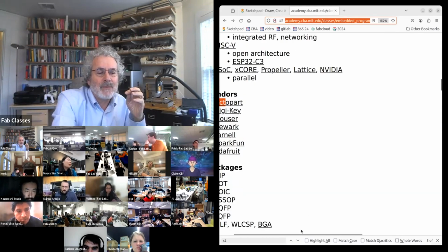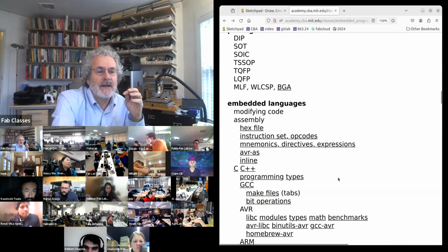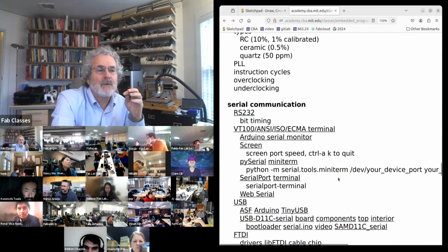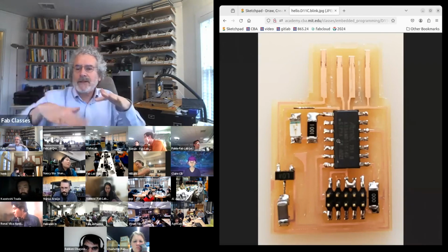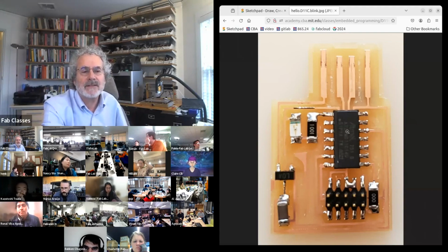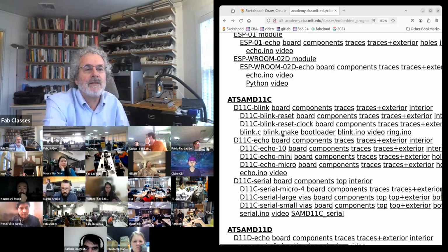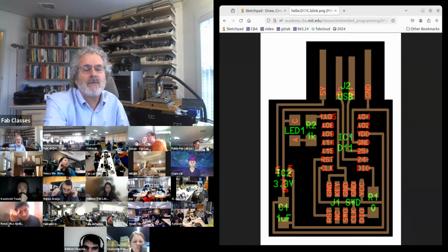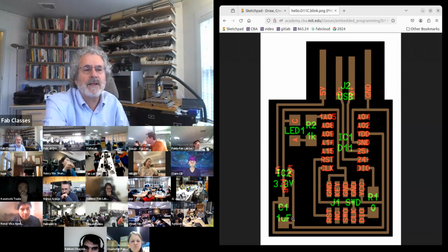So the reason I wanted to show that was down here, working with the chip is one level below the shell. It's the bare processor, and you make the parts around it. So in this case, on this board, we have a USB interface, the LED to blink, and USB is providing 5 volts. This is a regulator we use to bring it down to 3 volts.